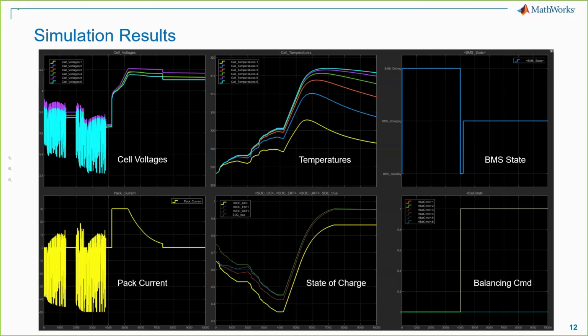Then we start driving for a while. When the battery SOC falls, we stop driving and charge our battery pack until it is almost full capacity. At the end of the driving phase, when the cell voltages are low enough, we limit discharge current to a lower threshold to prevent undervoltage situation. Now, while charging battery pack, we follow constant current and constant voltage, commonly referred to as CCCV charging method.